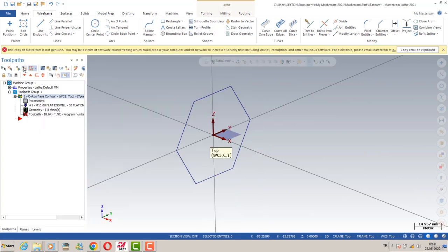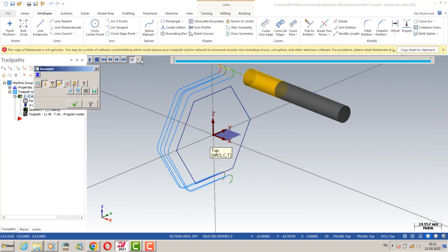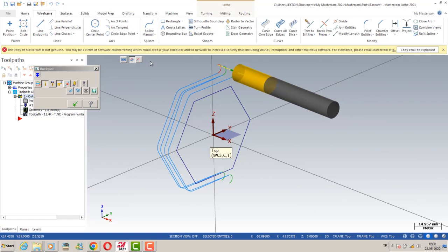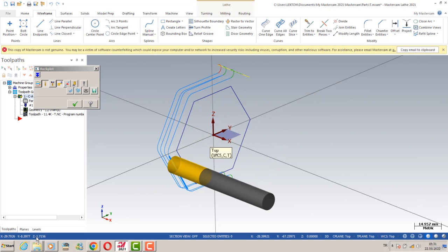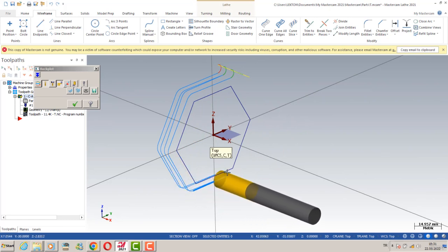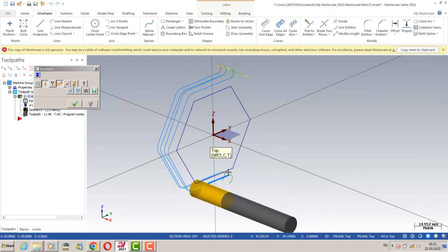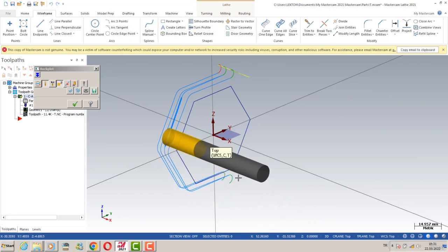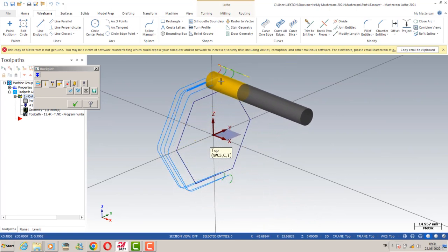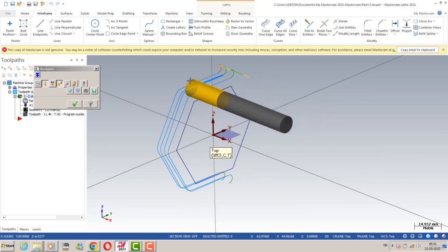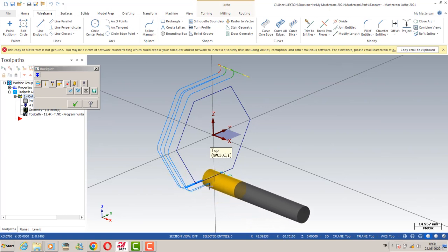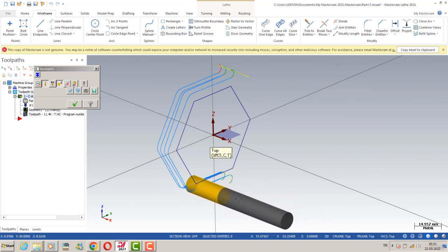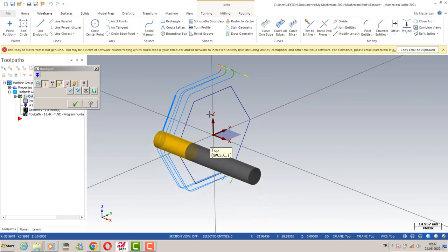At that point, you can see that these are the ramping options. When we turn to simulation mode here, we're going to see our ramp options. This is the Z position. It's going to reach -3 when we reach my final depth. After that, we can also start from here, -3 to -6, and then -6 to -9, and then as a final, we're going to see -9 to -10.